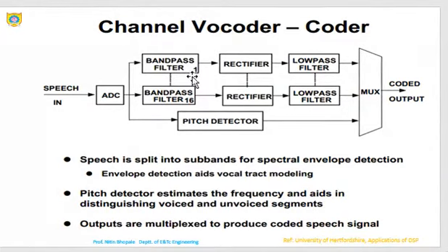While discussing the channel vocoders, there are supplementary parts. The channel vocoders split speech into increasing non-overlapping frequency subbands. The whole range covers the frequencies that humans can hear. Incoming speech is periodically sampled, typically every 20 milliseconds. The channel vocoder uses a multiplexer to send two different categories of information on the same channel. To multiplex two signals, take a sample from the first and then the second sequentially. The same cycle continues periodically.